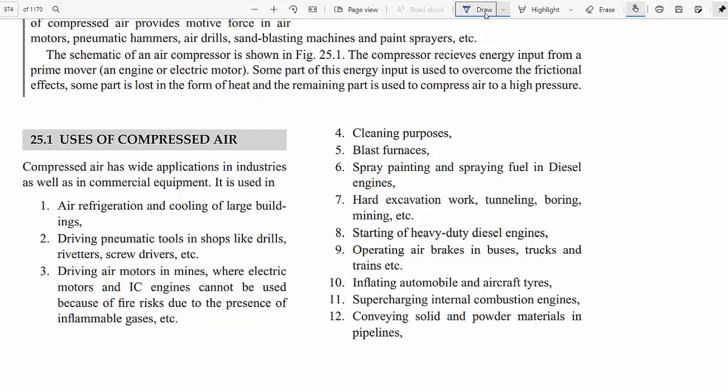You know, while we pull a diesel engine slightly, the vehicle is started. Likewise, we supply compressed air to one of the cylinders, then that cylinder is pushed down. Before the remaining cylinder is pushed up, the spark or diesel is ignited, and then the engine is started. So through the compressed air system alone, heavy engines and ship engines are started.